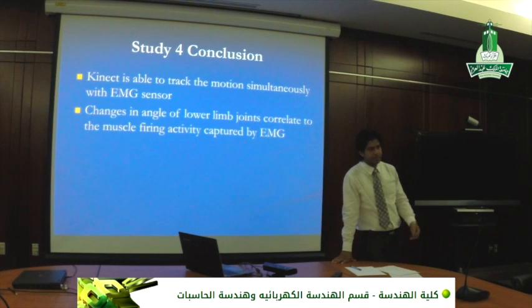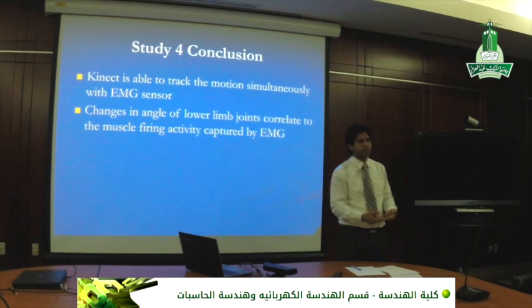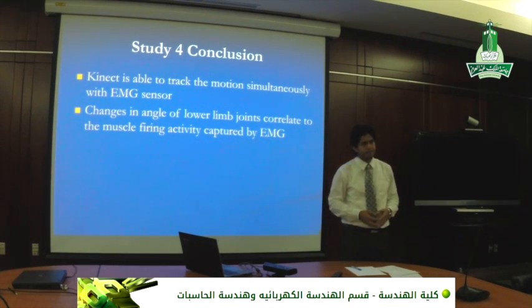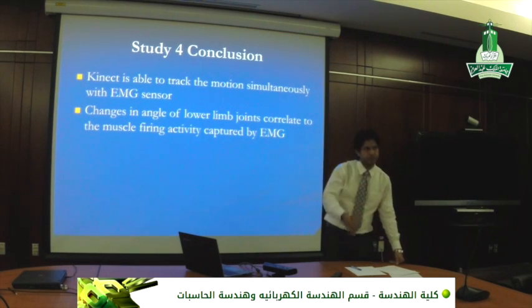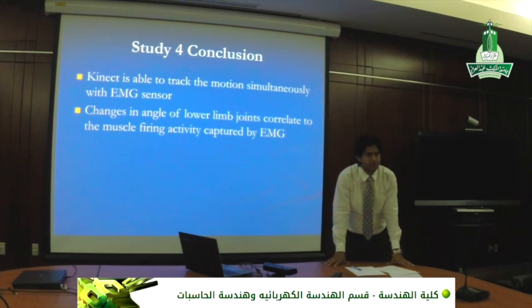The data that we are receiving from the inertial sensors is like a closed system that the company is giving. Does the company say that the sensor is giving you the motions? It is giving the changes in the angle. So that is rate. And once you are using rate, you definitely have to process it, because you are going to compare it with the absolute, real motion. How can you compare it with something that is coming as rate?